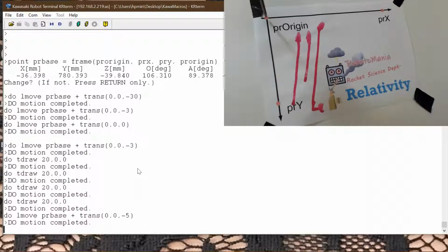So how do you do relative movements inside? Well, there are several ways, but what I would like to show you is the essential way, and we will use exactly that. I will make a transformation here that once reached this position, we will depart in the hand, in the tool coordinate system by 100 millimeters in the x-axis.